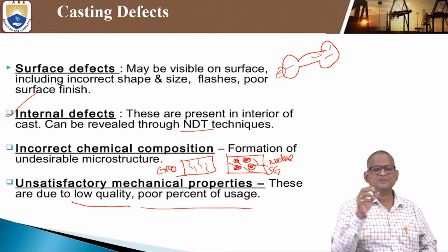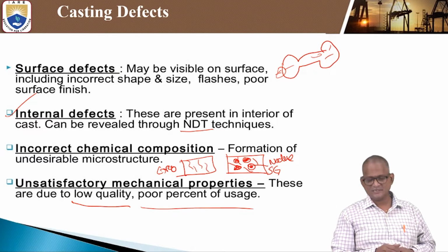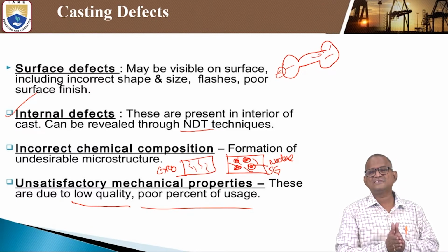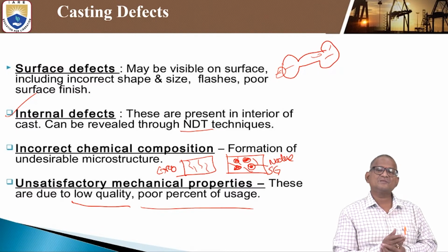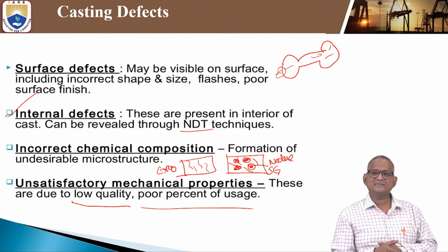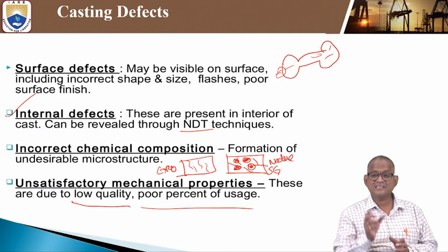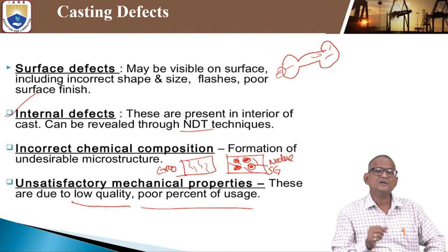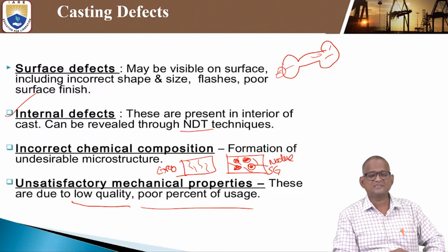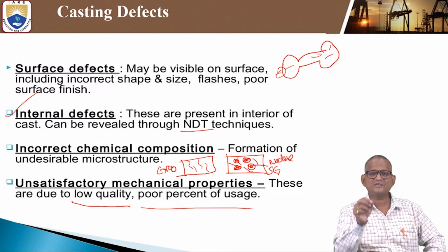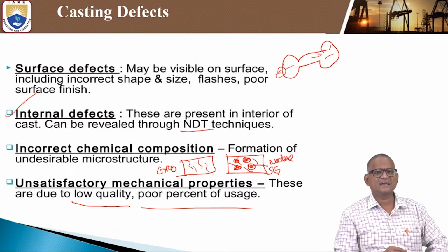There you check the ramming also, the preparation of the sand, the molten metal preparation, effective usage of the composition, and correctly the pouring time. Gating design also plays an important role in order to maintain good properties. The screw runner and gate design are also very important to obtain good mechanical properties.